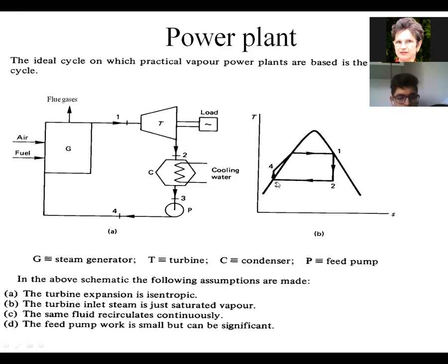And from 2 to 3, we have what? The condenser, yes, that is taking out the heat from 2 to 3. In the TS diagram, every area represents heat. So this squared form is the heat that is going out from the cycle.